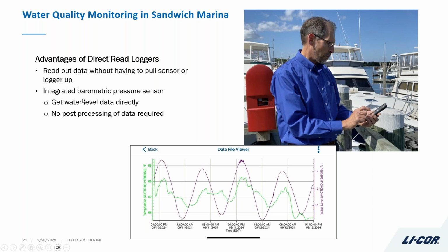And you can get the water level data directly without having to do any post-processing, because the logger includes a barometric pressure sensor in it, and it takes the barometric pressure and the water pressure data to calculate the water level. And you set the reference water level at the beginning of the deployment. So it's a pretty easy to use system.